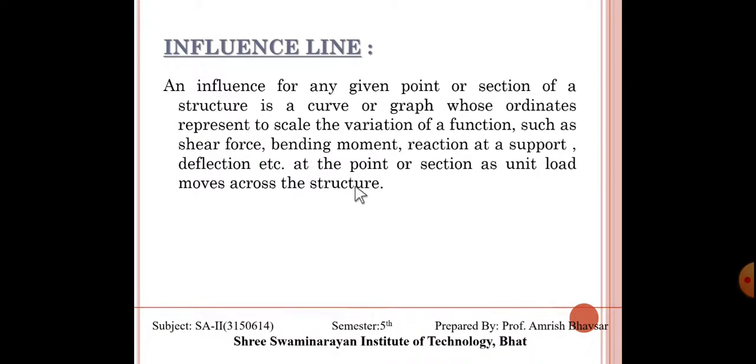But in some structures, there is a moving load, and that moving load will give us shear force and bending moment diagrams which are not the same as static, because whenever the load moves from support to span and span to support, it will create a fluctuation in the bending moment diagram.